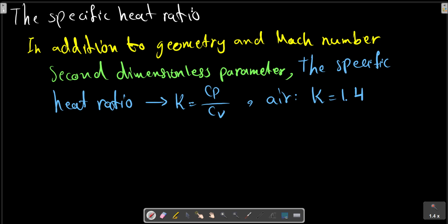Air is the dominant fluid of interest. Therefore, although we assign some problems involving other gases like steam, carbon dioxide CO2, and helium, the compressible flow tables available in this chapter are based solely on the single value of K for air. For other gases, we can also use the tables in Appendix P in the reference.